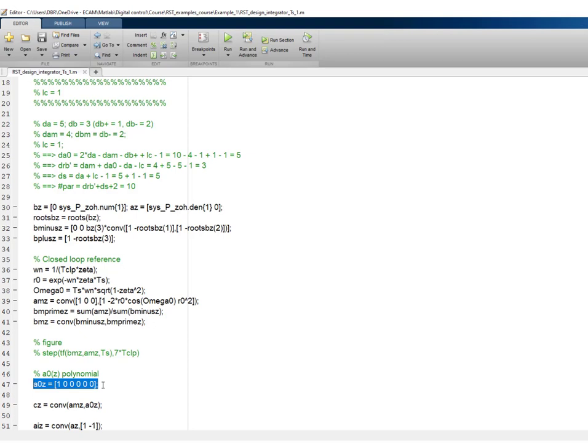If you're working on a system, you should experiment with observer polynomials and test if this is going to improve the robustness. And this is really important if you're working on an actual process. Here, the degree of R bar prime is 3 and the degree of S is 5. So we have 10 parameters over here.